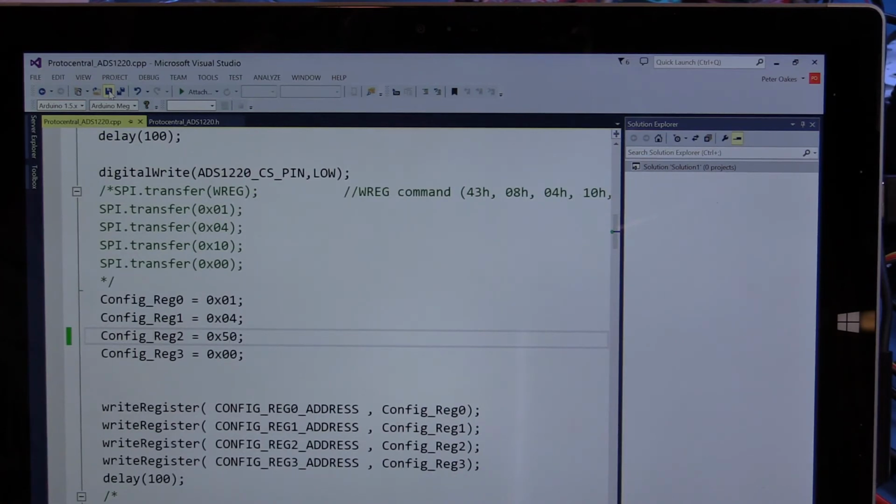If I set 1 volt, or 2 volts on the input, which I'm just setting up on my DMM right now, approximately, then normally it would show me roughly 200 millivolts from the 2.048. Because I'm going to 5, I expect that it's going to show me a little bit less than 1 volt, because I haven't changed the math yet in the code.